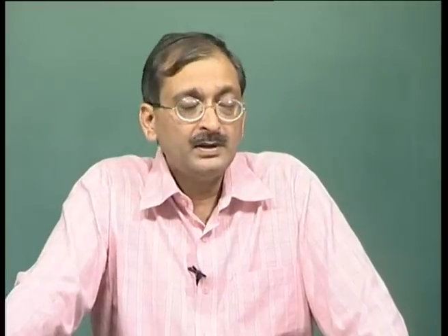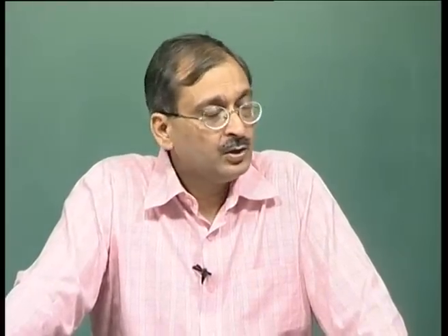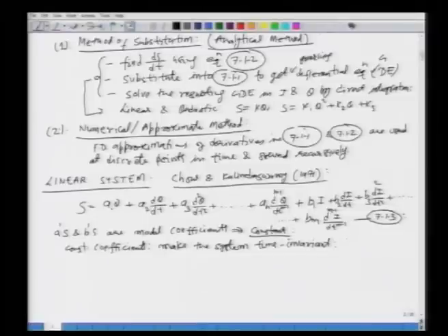Well, it means that the coefficients of your model are constant, so they do not depend upon time. If you apply this model, once you have calibrated it or developed the unit hydrograph, to data that may be in January, June, or December, you will get the same response. So, the coefficients do not depend upon the time, or they are time invariant. That is what we mean by that.